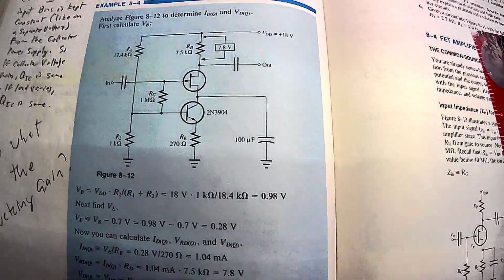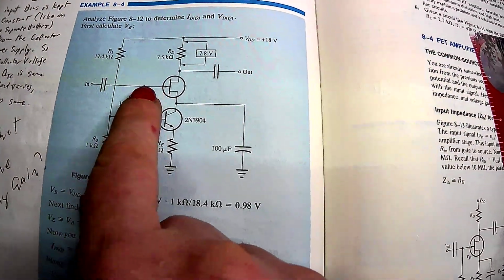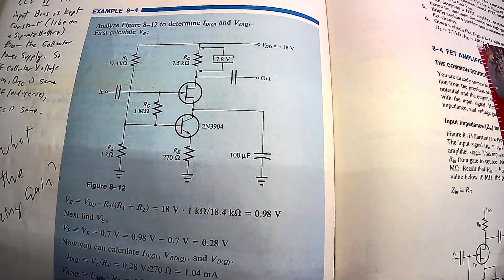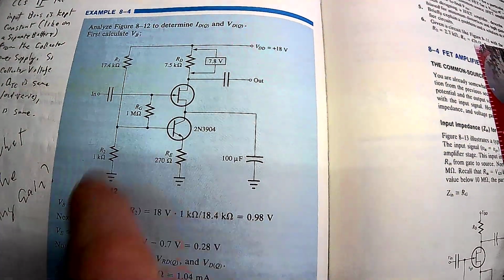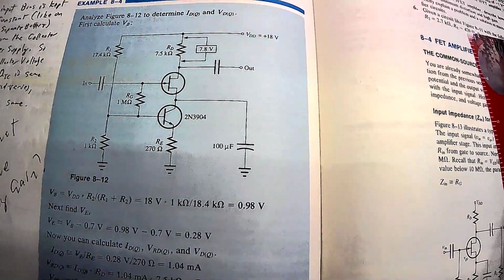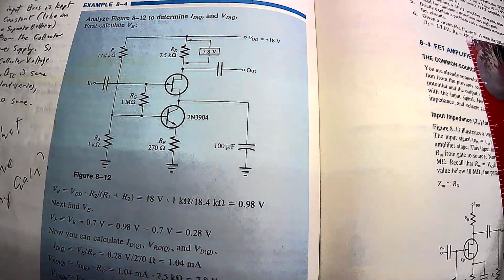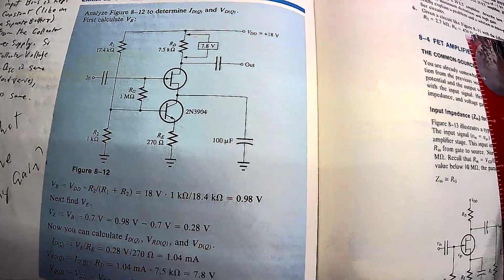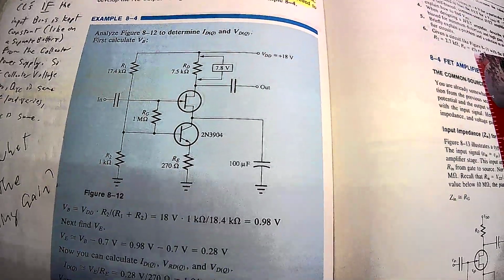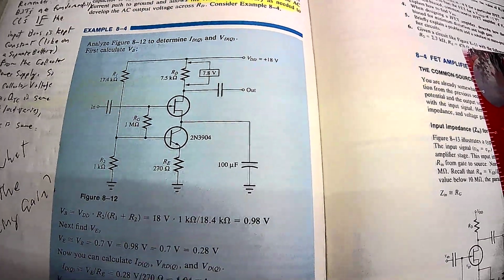So as a result, there's really not a lot you can do about the transconductance being different from device to device, even in the same part number, like I showed. So you're going to have a lot of differences. Even if you do something about some of the other parameter variations, you still will have that to worry about. So anyway, I just wanted to make that clear.